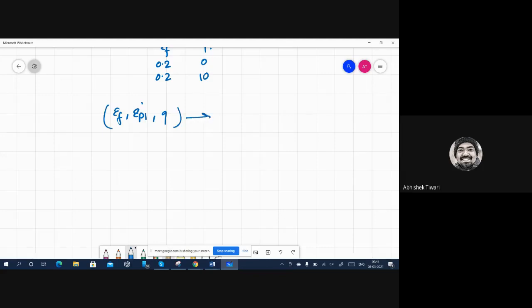These 3 points are going to tell me when omega will be just greater than 0. Omega is sometimes also represented as D, because D is damage. It means exactly when the damage initiates, the damage starts.